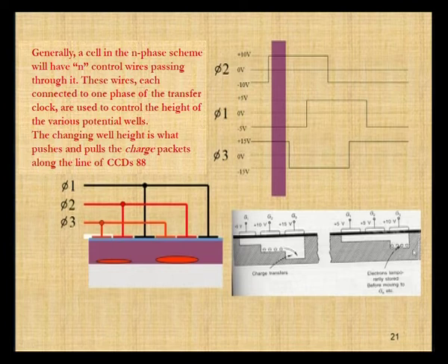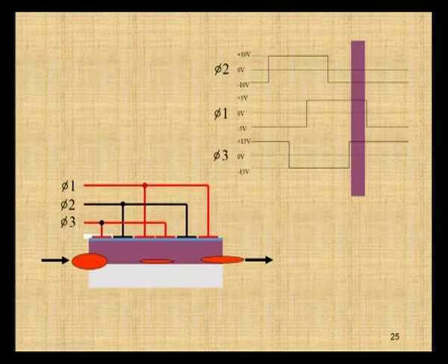It has to store the electrons in G3. After that, once it reaches the maximum value, the charge again moves to the next gate, that is G4. You can visualize the charge transfer like this: it is going to move and finally it will come out of gate 1, and again move to the next pixel. This is how the process of charge transfer continues from one cell to another cell.